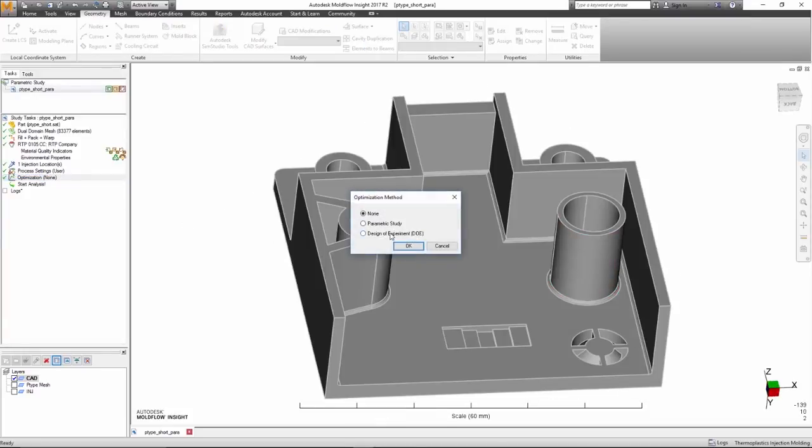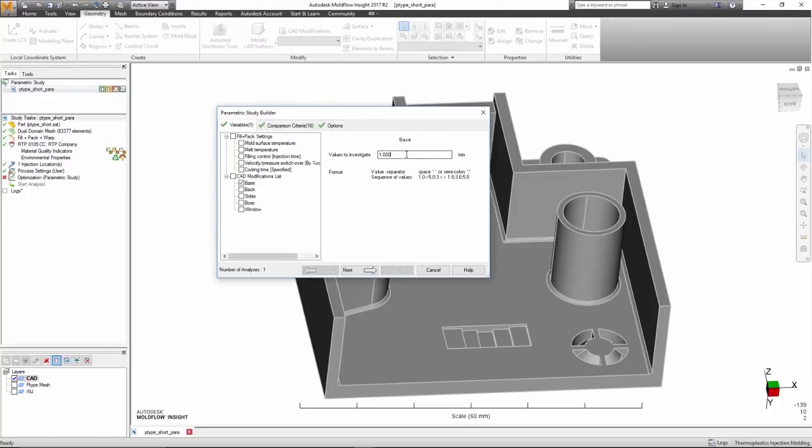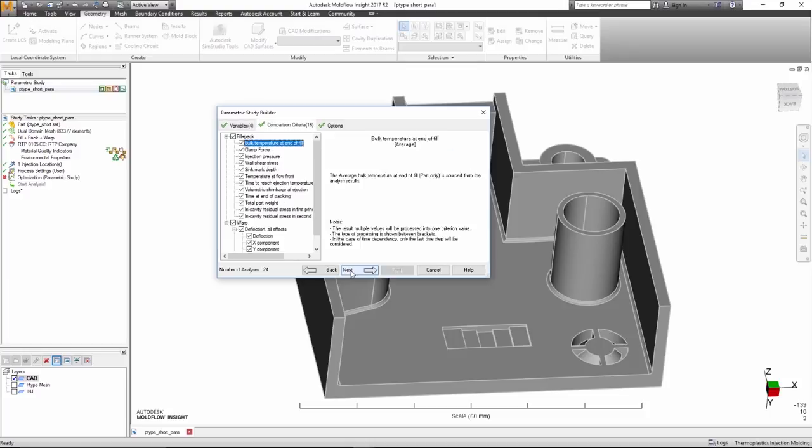Once the modifications are selected and saved, the user will go to the Parametric Study Builder. The design changes will be visible along with the other standard variables that can be adjusted. The Parametric Builder will attempt to create all possible permutations of the model and automatically mesh and run the analyses. The parametric study analyses can be submitted to the local machine or to the network. However, this is where the power of the cloud is priceless, as it will mesh and analyze all combinations simultaneously.